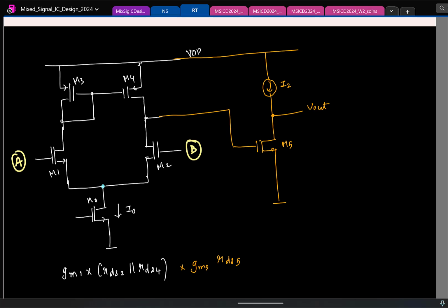Why? Again you can find, right? Let's say I increase this voltage. What will happen to this voltage? What will happen to the drain voltage if I increase the gate voltage? Come on, people, please wake up. Let's finish and move on. If I increase the gate voltage, what will happen to the drain voltage? Decrease. Awesome.